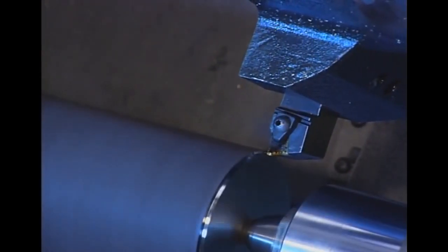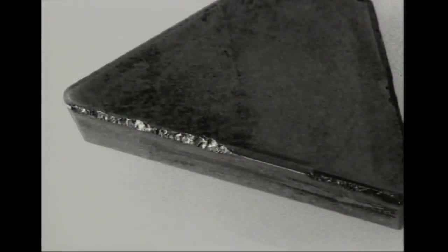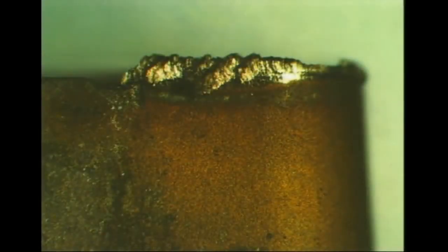The varieties of cutting tool wear include edge wear, flank wear, cratering or top wear, chipping of the tool edge, deformation, and the edge damage caused by the pulling away of material on a built-up edge. Two other types of tool wear are thermal cracking and notching.